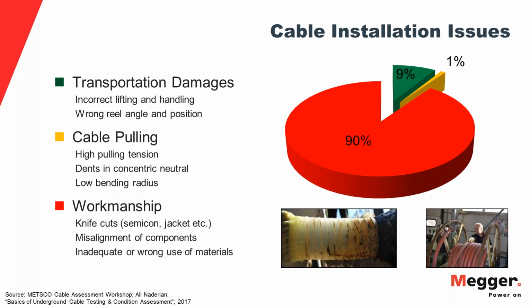But those are two things that you see very often: incorrect storage, and not taking care of the exposed parts during installation, so more moisture ingress than would naturally happen. And of course, transportation damage, incorrect lifting, and wrong positioning on the trucks.